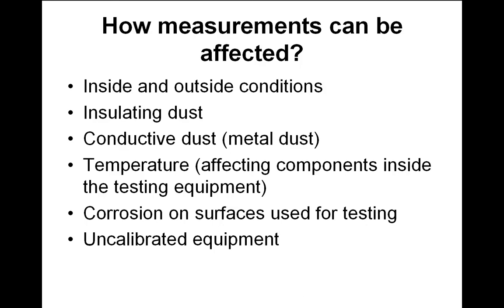Did I mention it last time? I don't know. Whenever you've got a meter, you should always have spare batteries. And most of them use these 9-volt batteries. Some meters have weird specialist batteries. I know the AVO has got a specialist battery. So you should always have a few of them around and have a few fuses as well for your meter. So just in case you make a mistake or an error and the fuse goes, and you can't use it for current measurement anymore.